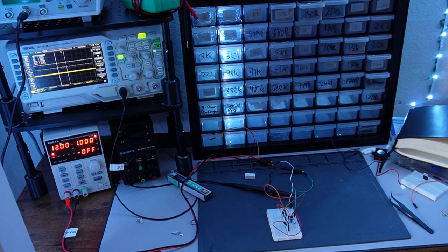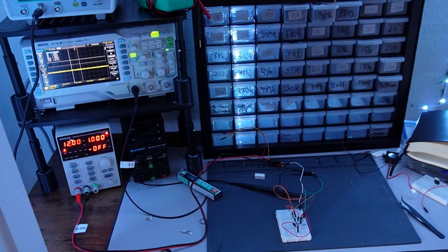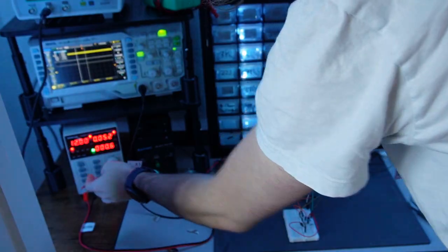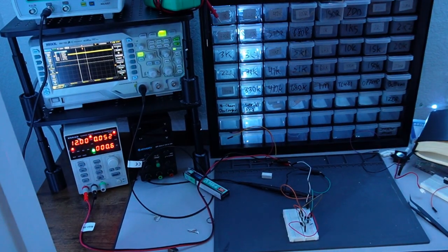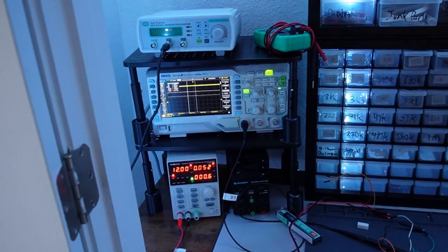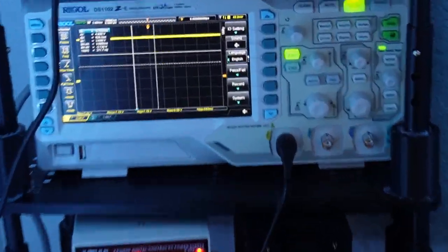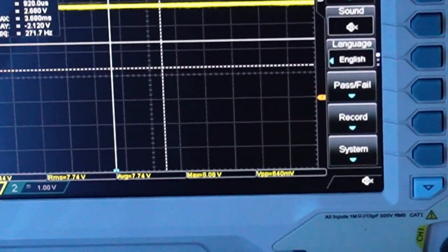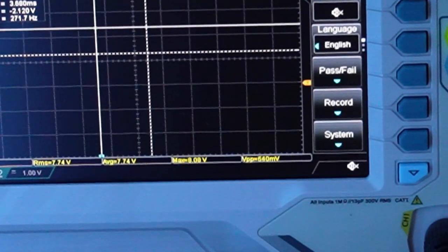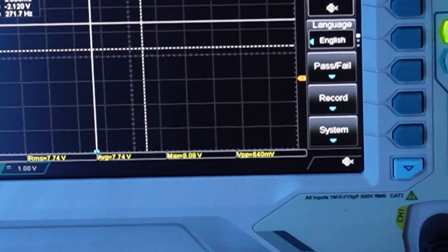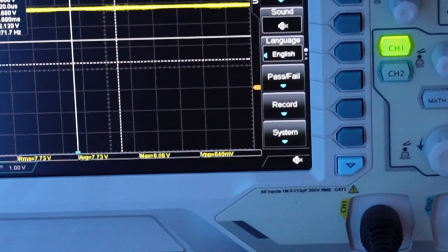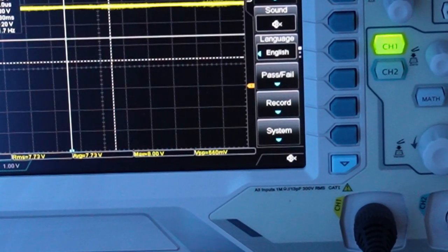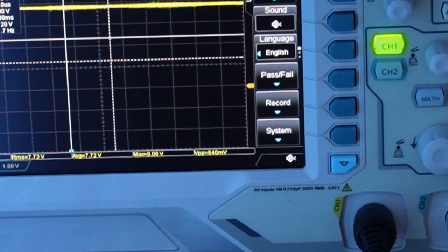So because of that, we will see some minor modifications, but if I turn it on, we can see on the oscilloscope the voltage, and this is tied to the collector currently, we see that we have around 7.74 volts. And the truth is, we had a reduced collector resistor, so it's going to have less voltage drop for the collector current.